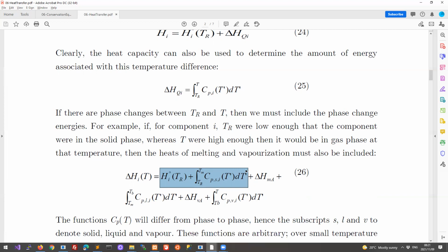And then to cross over from 0 degrees into a temperature just more than that, so where you are all water, you need the latent heat of melting. So you need all that water to melt. And this is not covered by your heat capacity. Heat capacity assumes that we are in the same phase, whereas we need to reach from solid water to liquid.